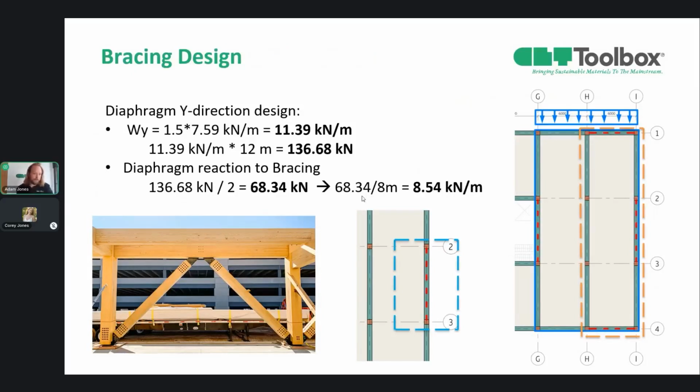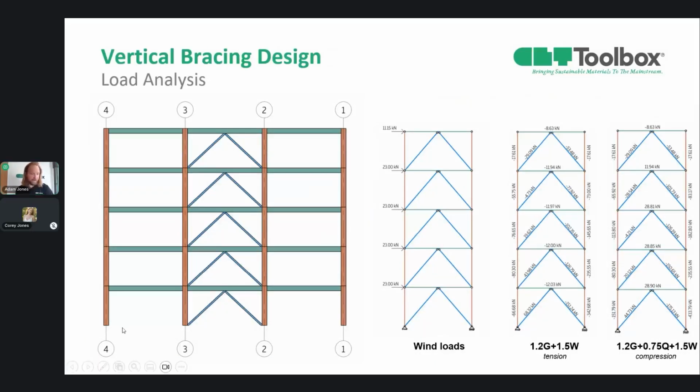All right, so bracing, we can do the initial calcs. Again, from an early stage project, you could do this relatively by hand, get the elevation, work out the forces based on the wind loads, run it through an analysis to work out the forces, and the governing force being the bottom element of the K-brace, as you can see here.